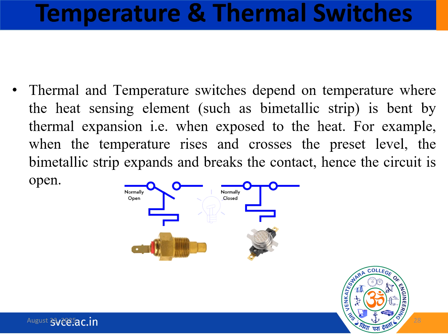When you consider the operating principle, the bimetallic strip is composed of two metals with different expansion rates. That we call the sensing element, and temperature rise causes bending due to differential expansion, right? That process we call the trigger mechanism, so action can be taken. Contact is broken when the strip bends beyond a critical point.